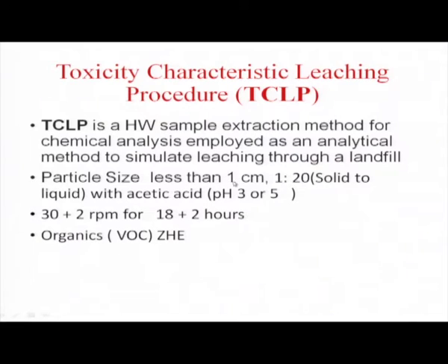That sample has to be collected and the particle size should be reduced to less than 1 centimeter before subjecting it to the test. That is the first step. Any bulk particle, the size should be reduced to less than 1 centimeter. Okay. And then next, by checking the pH of the particular waste, there are two fluids available.